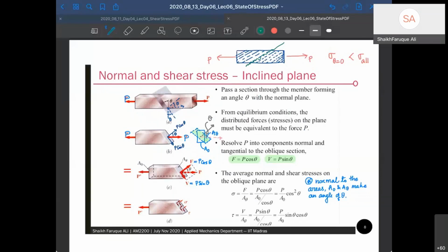The point is, when you looked at this stress, you looked at a plane that was this. You did not look at this plane. What will happen at this plane? What are the stresses acting at this plane? Where were these stresses higher than this and higher than this, or lower than this and lower than this? You did not check that. You need to check that. First point. Second point, you checked for normal stresses.